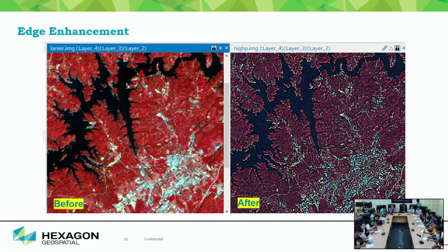Edge enhancement. Here this technique is very important. This is the water body. Can you see that some pixels are there that might be due to shallow water, or some sand part, or the moisture level is higher? Water is not represented there, but moisture in the soil is why it's looking like this. But when you use this image enhancement technique, the edge enhancement technique, then you can see that the edges are looking very clear. So now you can quickly digitize this, right? Here the chance of error is minimized a lot.